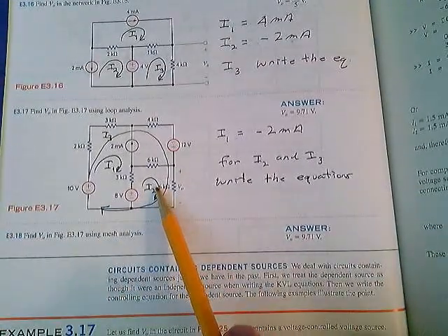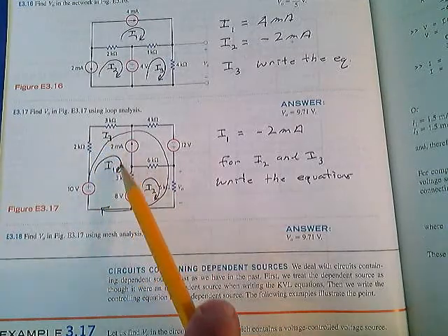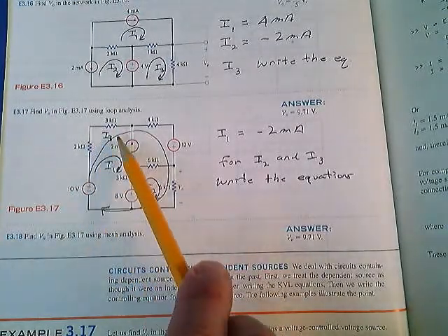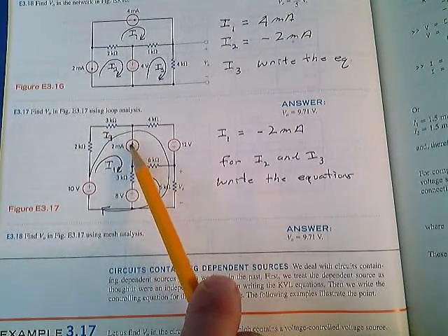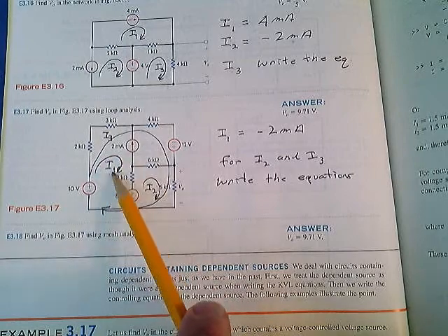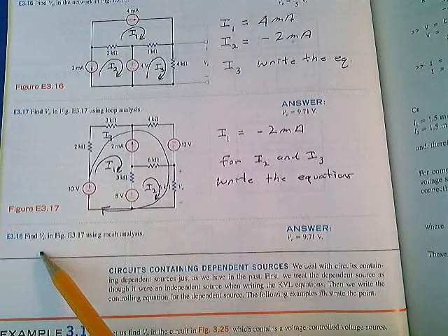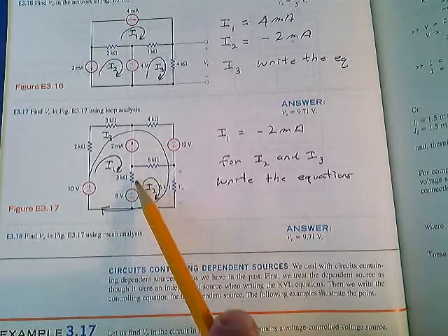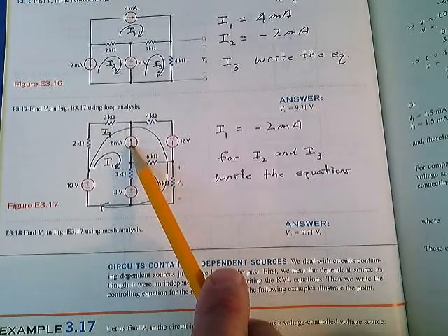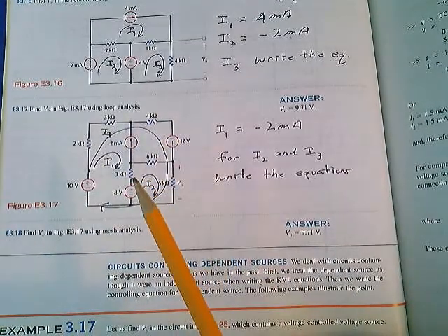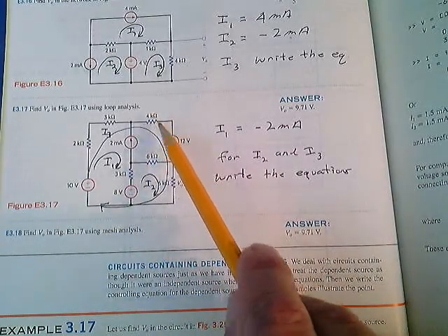And down here, I assign current I1 in this direction. This was all I1. So if this is I1, it's gone through this current source, and it's going to be the only current going through that. You'll see this in a minute. So by inspection, I1 is minus 2 milliamps. So how do I assign I2? Well, I can go around here and assign this loop current I2 and write an equation for it. It doesn't interfere with this. But how am I going to pick up these two elements here? Because there's nothing gone through these yet.